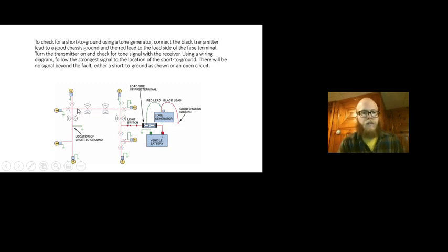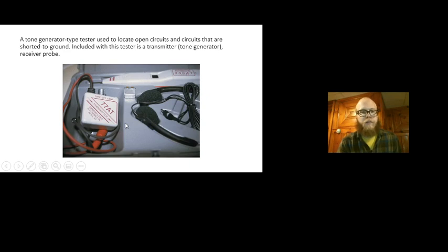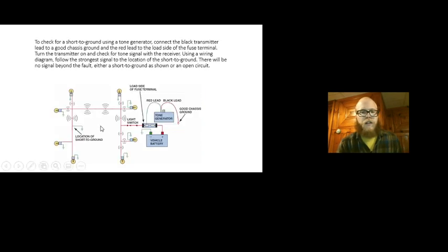Oh yeah, magnetism. We get here, and the voltage or the current flows to the short because that's low resistance and easy, and anything past that won't have any current flowing through it, or not much to speak of. And so then all of a sudden the little needle would stop working. Or if we're using our high-speed headphones that can pick up noise from the tone generator, then we would stop hearing noise as we went along as well.